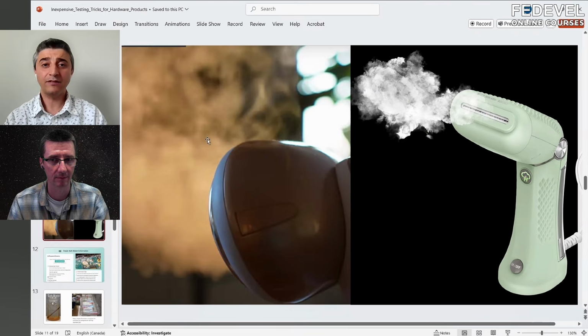There are designs that are conformally coated, PCBs coated for protection against dust, particles, and high humidity. So how would you find out if your conformal coating is working as expected? You can take the steamer and apply it on top of the highest-risk elements on your design.